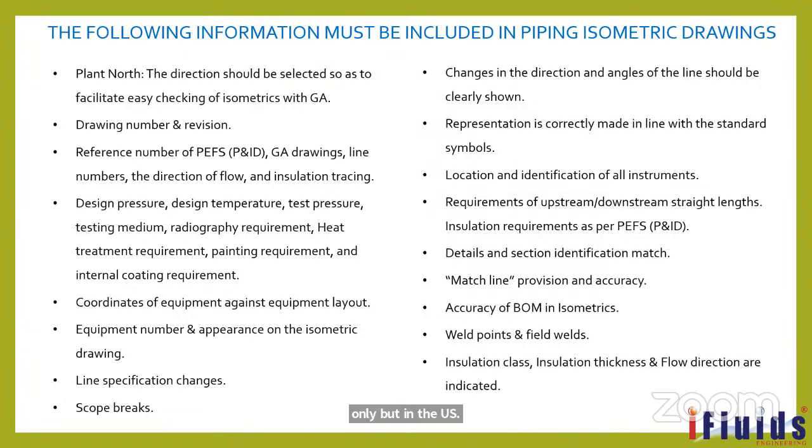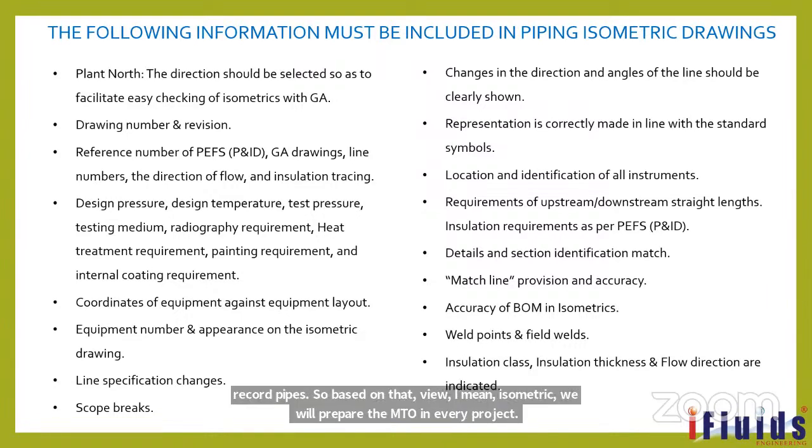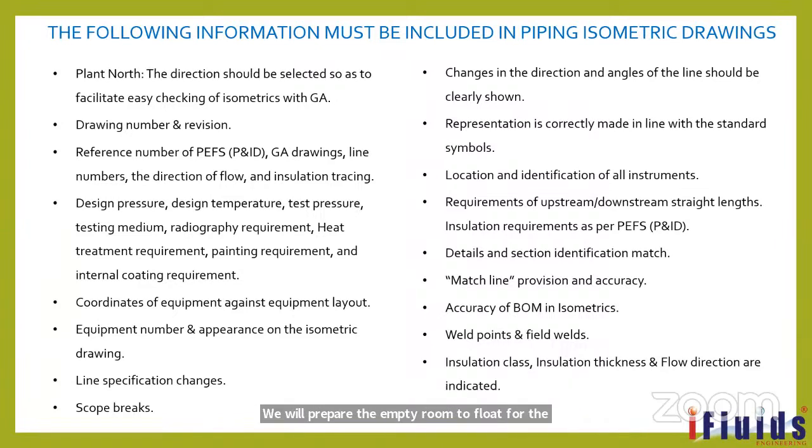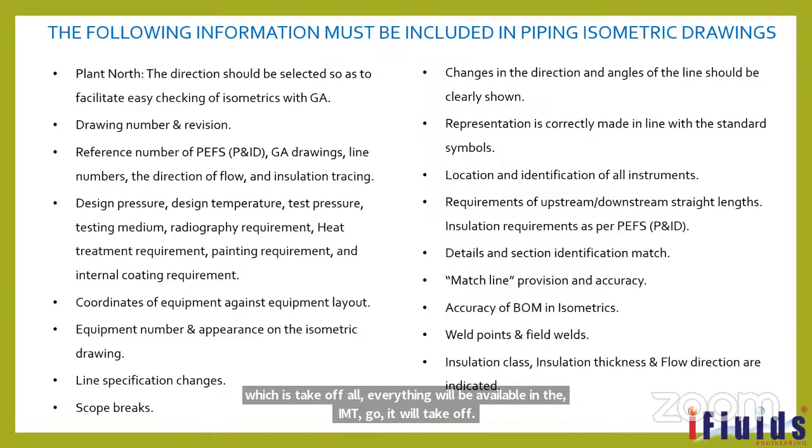Based on the BOM and isometric, we will prepare the MTO. In every project, we will prepare the MTO to forward to the purchase department. MTO means material takeoff. In that, it will clearly be there: for 2 inch, how many meters, how many kilometers are required; for valves, how many hundreds are required, which type of valve. Everything will be available in the material takeoff. That material takeoff base we will take from the BOM.